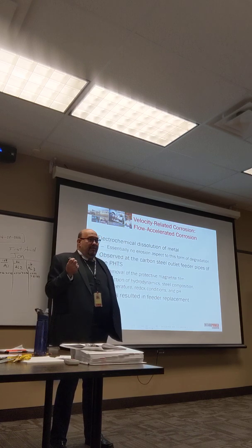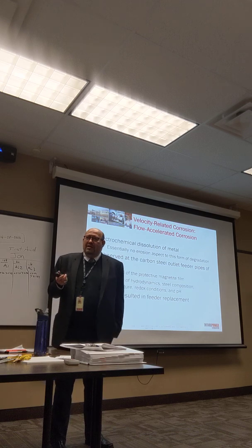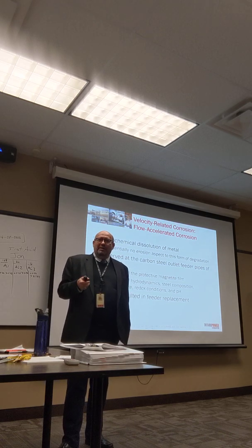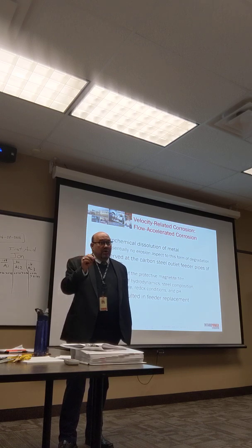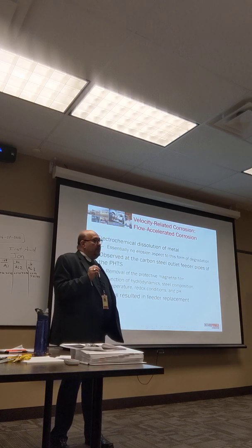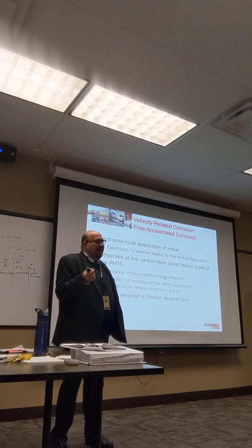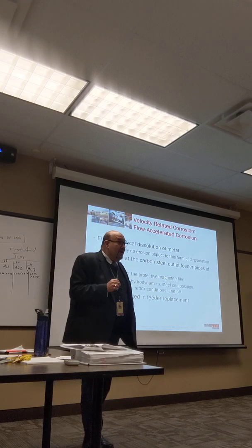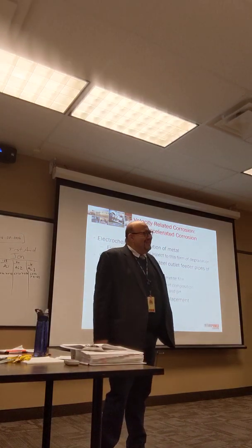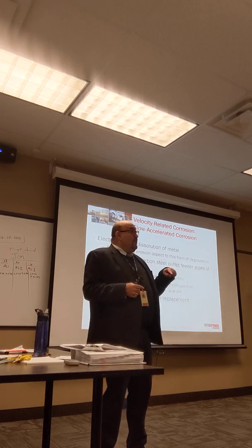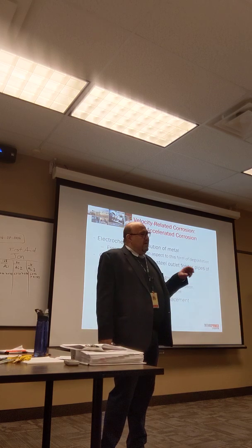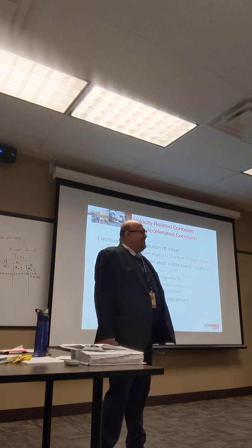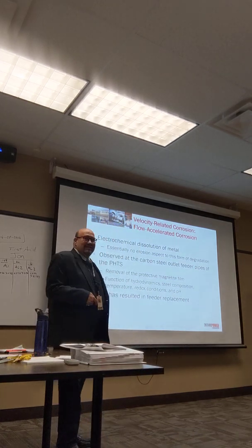It's working fine. But now we are carrying more appetite for mitigating these effects. It's just an appetite. The newer feeders in Darlington, I think they've increased the chromium content. I think they have 0.3%. Very good. So the chromium actually will stabilize this passive layer. It's not stainless, but it has just a hint of it.